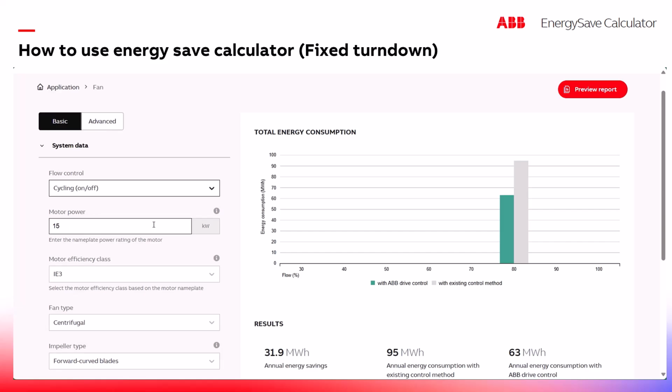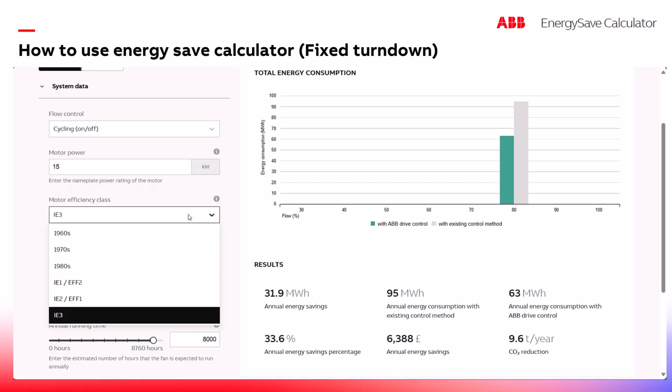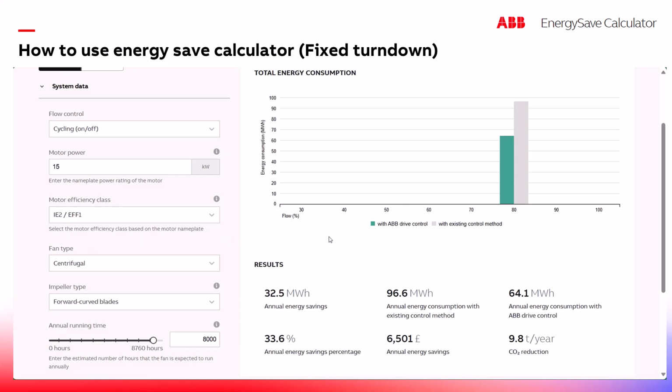The motor power that we're looking at is 15 kilowatt. So you just enter the nameplate power rating of the motor that you're looking at for this application. So the next one is the motor efficiency class. So you've got all the options in here. If you've got something really old from the 60s, 70s or 80s, you can select those, which will give some reference data. More realistically, I'm going to select IE2 as a reference more to what we're looking at.